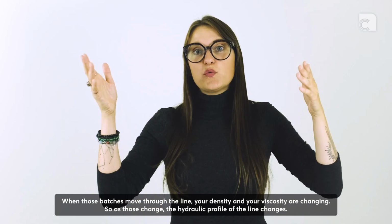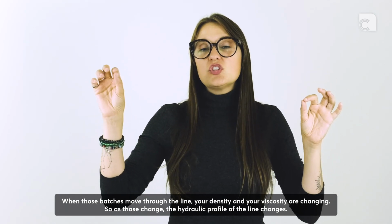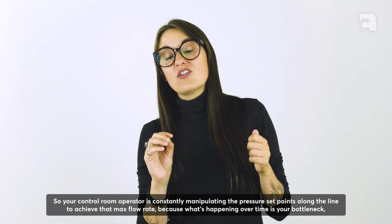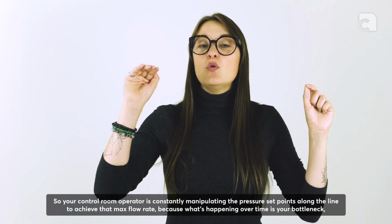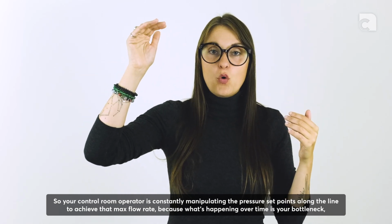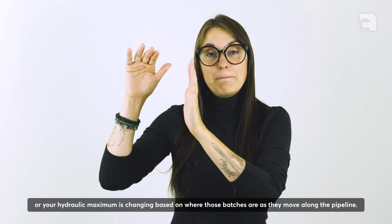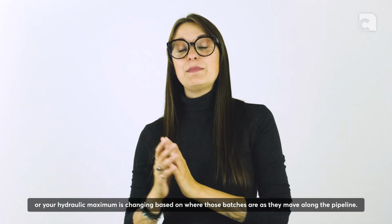So when those batches move through the line, your density and your viscosity are changing. So as those change, the hydraulic profile of the line changes. So your control room operator is constantly manipulating the pressure set points along the line to achieve that max flow rate. Because what's happening over time is your bottleneck or your hydraulic maximum is changing based on where those batches are as they move along the pipeline.